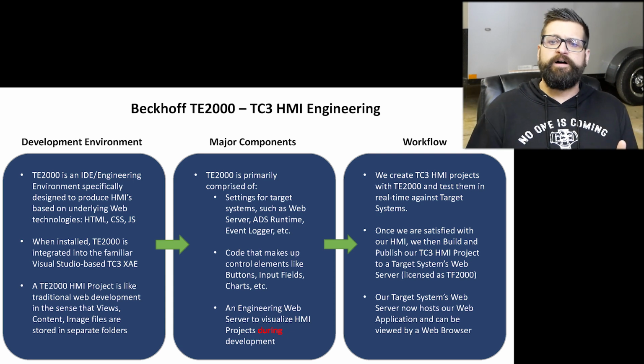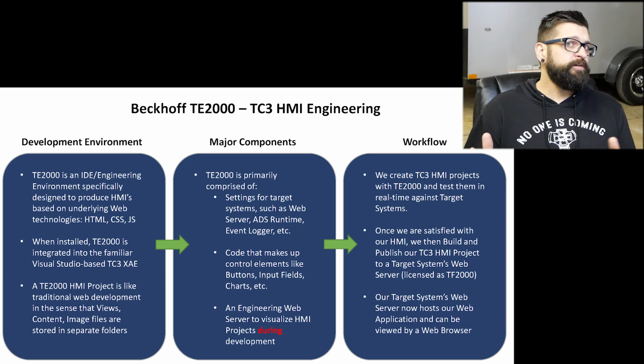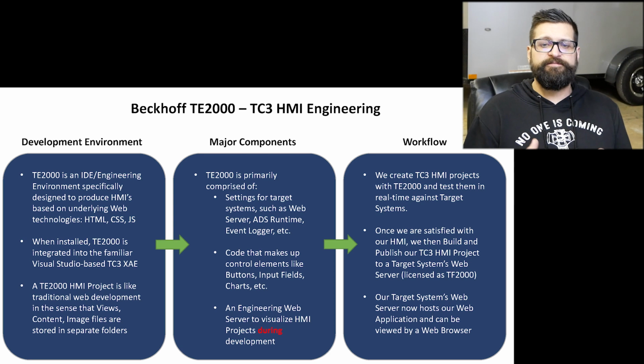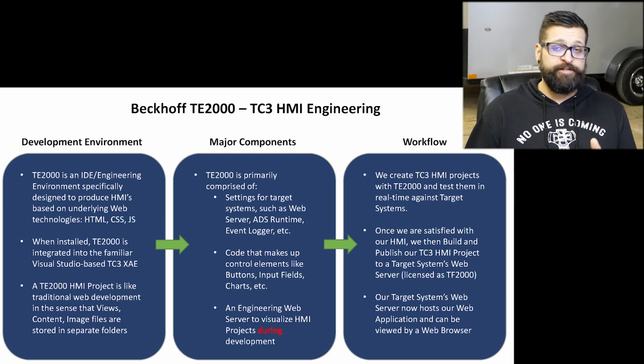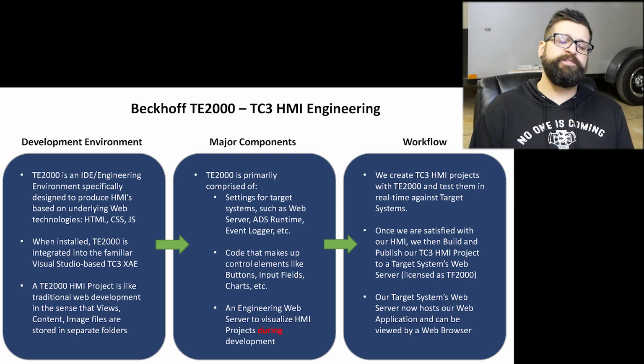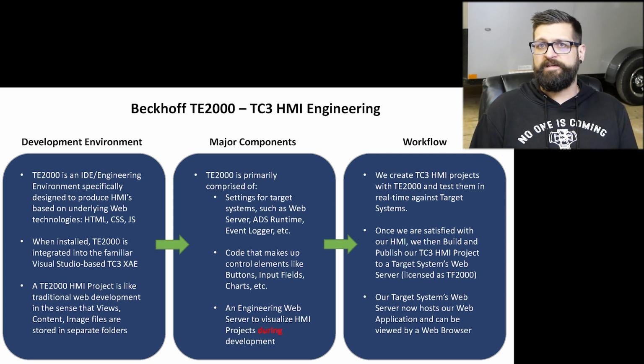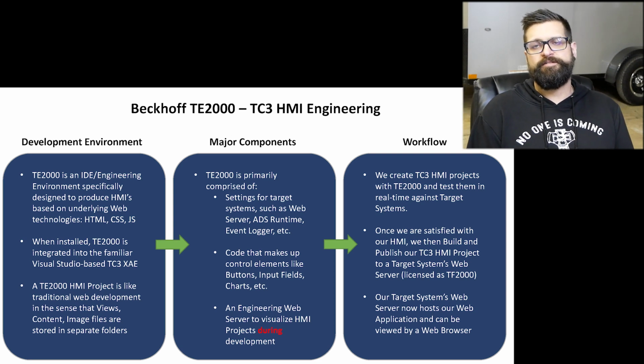And so the workflow that we have, like I kind of addressed already, is we're going to create an HMI project. We're going to test it against our real-time PLCs. So if you have actual controllers that you're running, or if you're just testing it locally by spinning up a VM or spinning up an instance of a PLC on your computer, you can test that with that target system in real time.